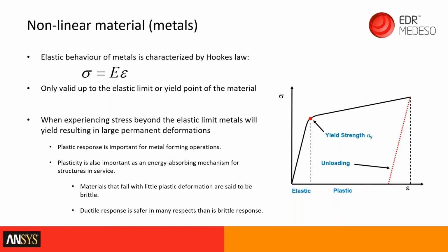So if you're not interested in what happens after yield, you can use linear materials. They work quite well. For most engineering applications, you're not wanting to yield the material beyond the yield point, and you're not interested in plasticity. But there's a lot of applications that Ansys has applied to where you are interested in the plasticity.